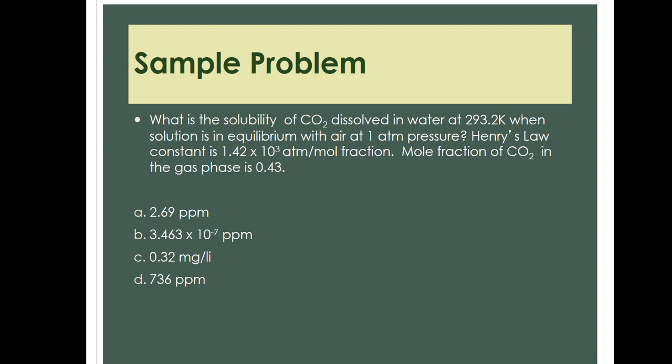Henry's law constant is given already with a value of 1.42 times 10 raised to 3 atmosphere per mole fraction. Moreover, the mole fraction of carbon dioxide in the gas phase is 0.43. Take note that the problem is talking about the mole fraction of CO2 in the gas phase, which is 0.43, but it is asking for the solubility of CO2 dissolved in water.